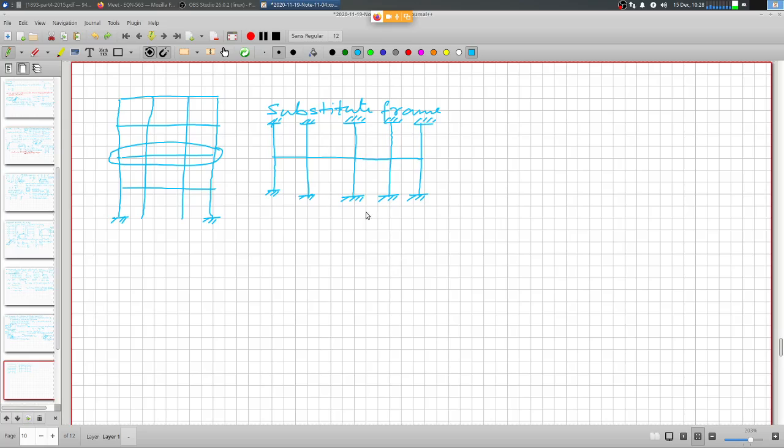right, and the loading on this particular beam being defined by the tributary area, load coming from the tributary area of the slab on that floor, and you can see this is the tributary area that you may have, and it can be rectangle, triangle, trapezoid, some kind of thing.